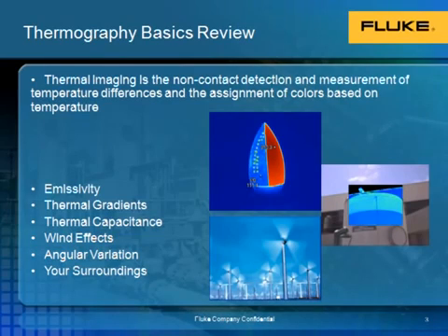Thermal capacitance refers to a material's ability to retain its temperature or its heat energy. We see this come into play on the picture on the far right of the tank level. Because water has a high thermal capacitance, it retains its temperature a lot longer than air, for example. So the air above the water within the tank allows us to see that fine line and the level within the tank. It's important to be cognizant of wind effects as well.